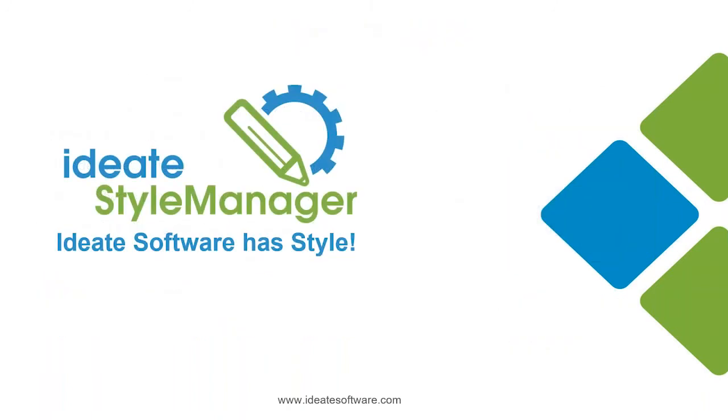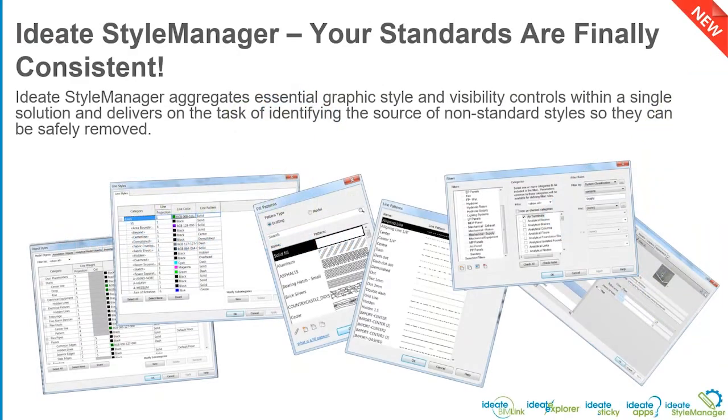We're going to talk about Ideate Style Manager. Style Manager was developed by Ideate Software because we saw a big problem in Revit projects and templates getting out of hand with all kinds of styles that don't match our standards. What happens, and I'm sure everyone knows, is you load content from a third party, or copy information from one Revit project to another, or you import or link in AutoCAD or MicroStation information. And then all of a sudden, your object styles and your line styles and your line patterns are all over the place and they don't match your standards.